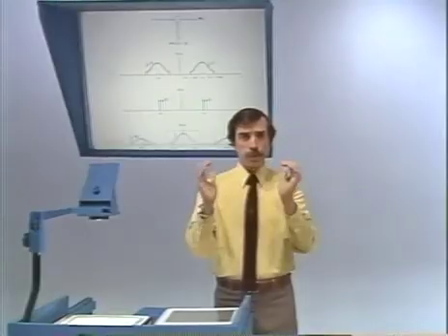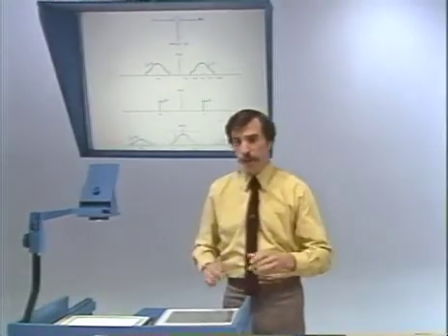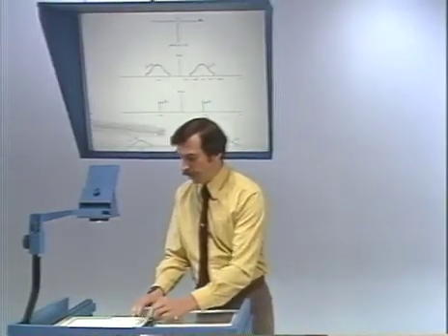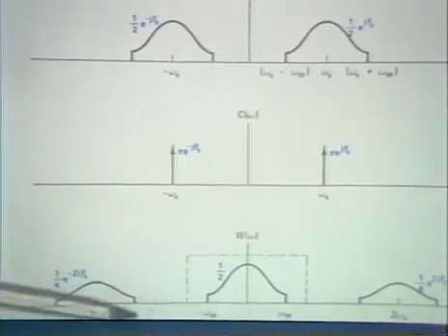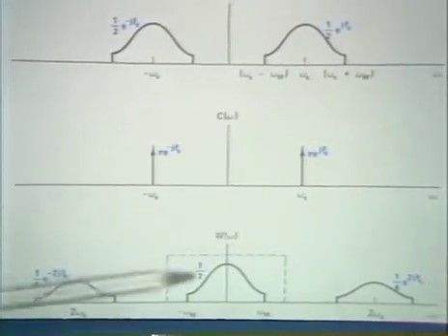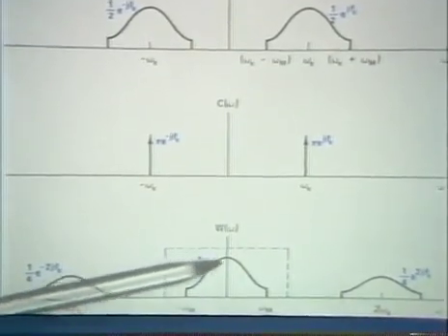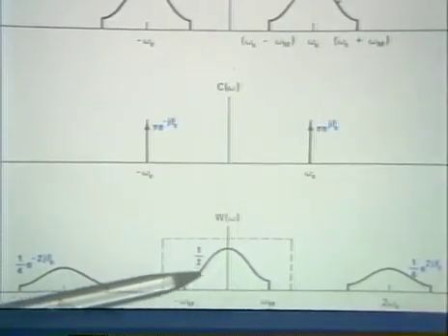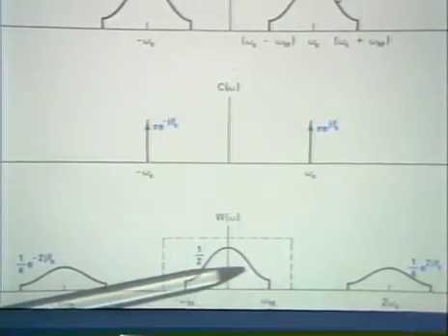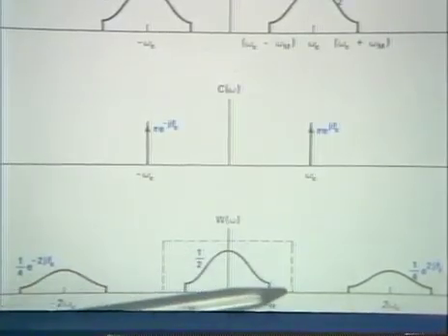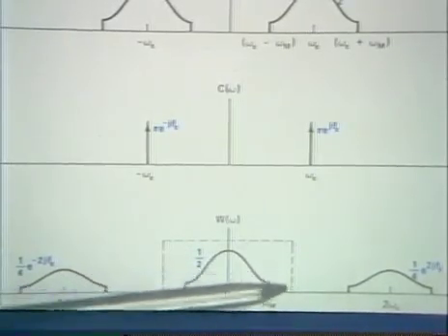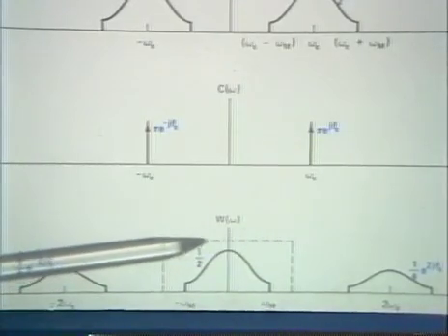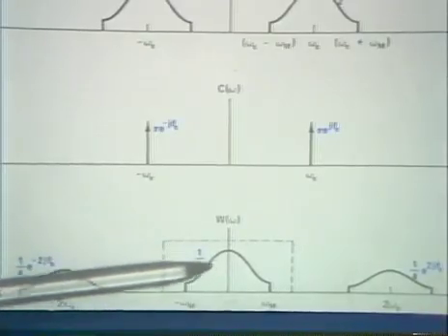The low-pass filter would retain the part of the spectrum around DC and eliminate the remaining part of the spectrum. So we would keep this part and eliminate the part of the spectrum that we have over here. And let me just draw your attention to the fact that because of the way the algebra works out, the amplitude of this replication of the spectrum is half what the original spectrum was, and that means that ideally to keep scale factors correct, we would choose the amplitude of this to be 2 to scale this back up to 1.